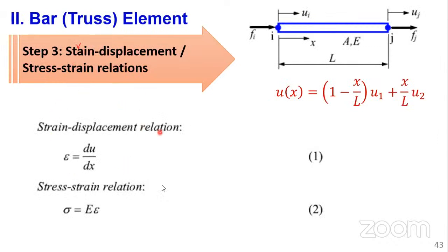So basically, if I take you back, this stage and the second stage, we could not do with the spring element, because we said the spring element is not suitable for stress analysis. For stress, you need the cross-sectional area of the spring, but our spring is coiled, helical.